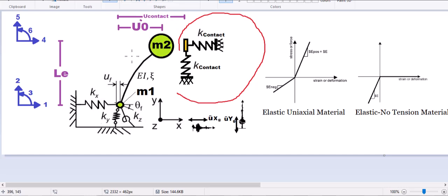So if, during the seismic acceleration, the displacement reaches this contact displacement, the structure has lateral springs in the x and y directions that are going to be engaged and connected to the structure, trying to damp the total response of the structure from this node.